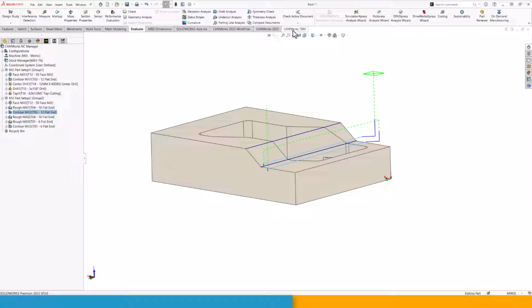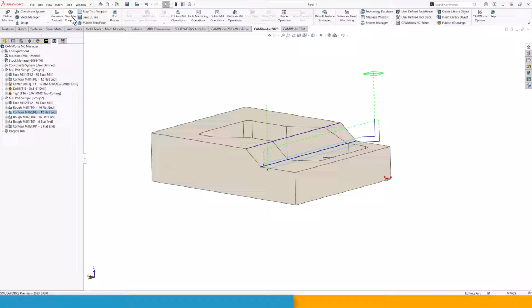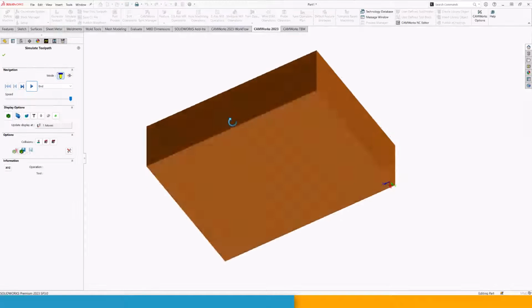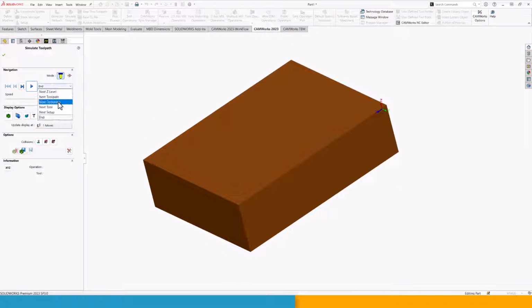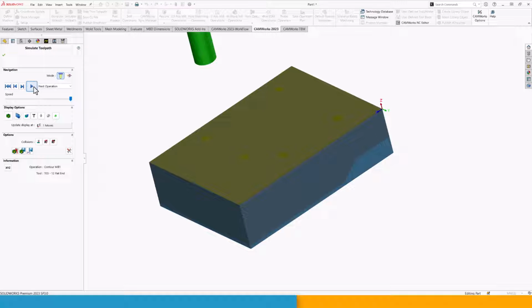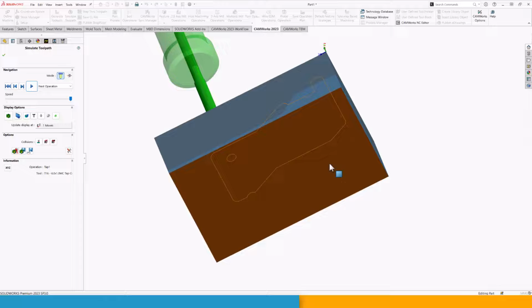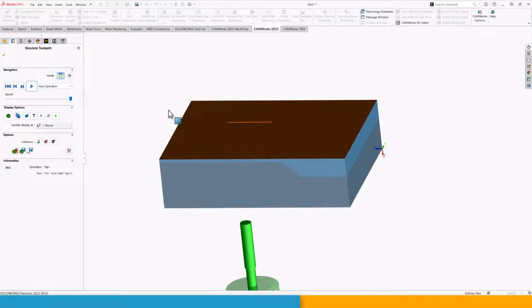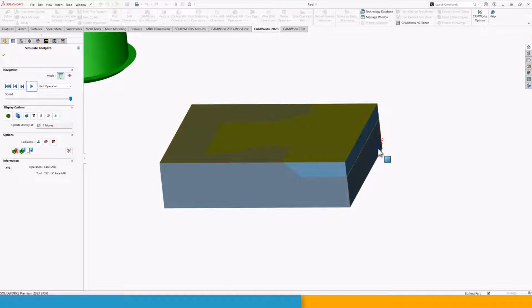let's just run through the simulator and see what we got, and then adjust a few toolpaths as we need. So starting from this side, let's go next operation. We face mill, machine the perimeter, we drill with a spot drill, a true drill, and a tap drill. Then we flip it over, and I can see that my 0 point is actually located incorrectly, and let me cover that as well for you guys. Now this was the face mill, then we are going to rough away this area.